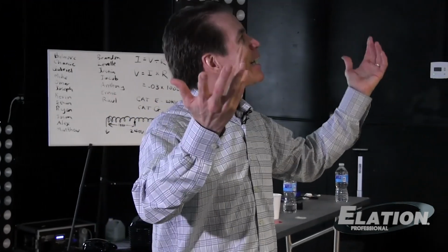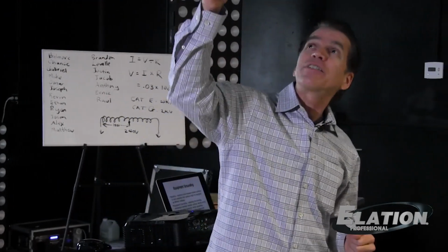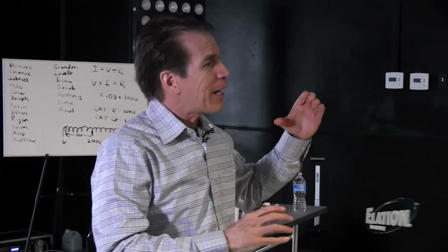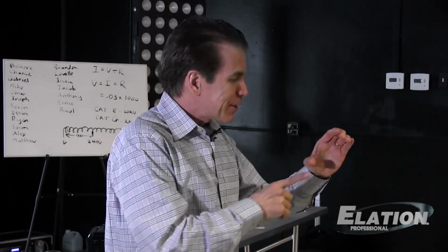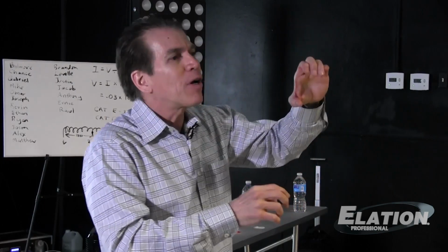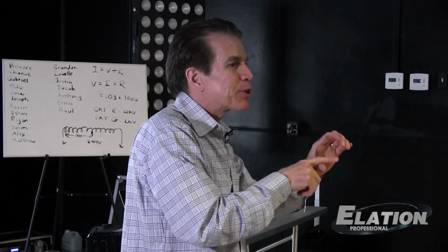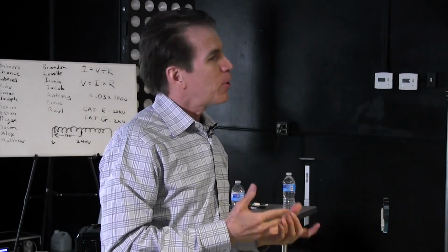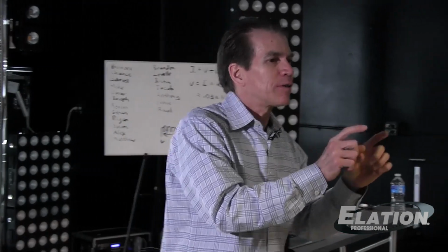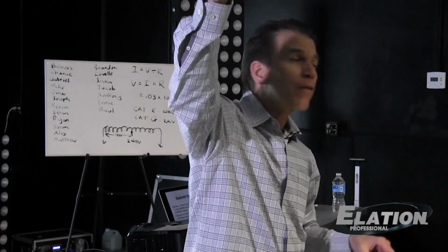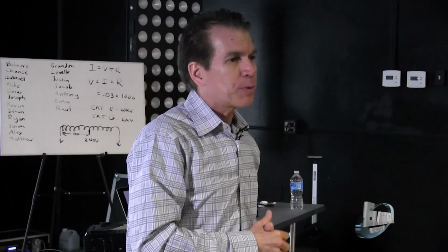It's nice and shiny. And then you take a C-clamp, like the old style cast iron clamp. It's got the bolt through it, and you hook it on there and tighten it down, and it puts a dent, it puts a scratch on that truss. So what do people do? They'll take a PVC sleeve, they'll put the PVC on the chord of the truss to protect it. They call it a truss protector.